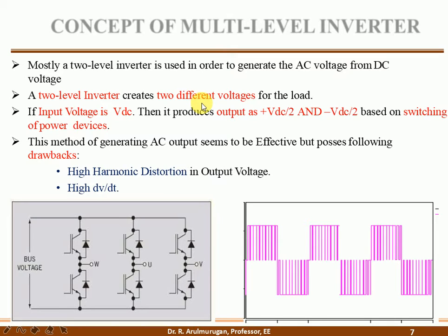And then the half bridge inverter and the full bridge inverter. On the source side, if a capacitor is used in a half bridge inverter, they use two capacitors and two switches. The two switches and the capacitors are used to divide the source, so the source value is divided into plus VDC and minus VDC.